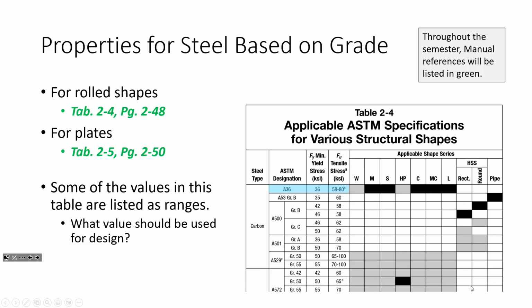Okay. How many of you have ever heard of the Northridge earthquake? How many of you have heard of that? In California, yeah. This was a major earthquake in 1994. Okay. Now the steel industry was telling people during the 70s, 80s, they were saying use steel moment frames all the time. Okay. They were saying use them all the time because steel moment frames are incredibly ductile, and ductility is a parameter that we really like to see in earthquake design. That's great, okay? Now, here's the thing about material specifications, okay?